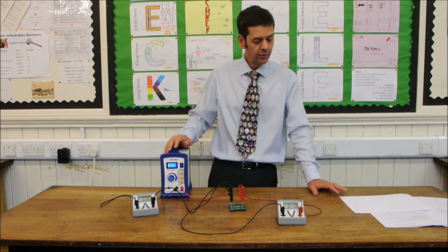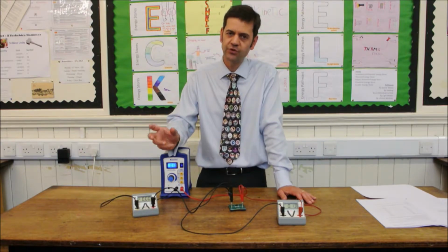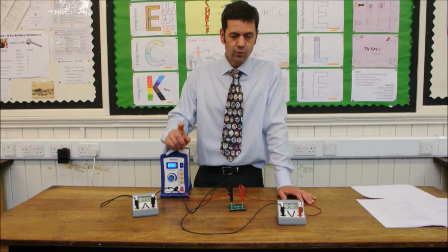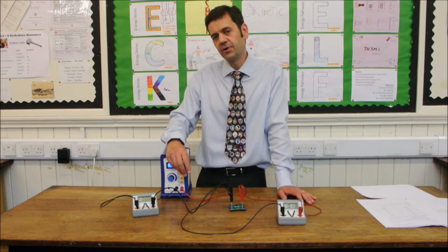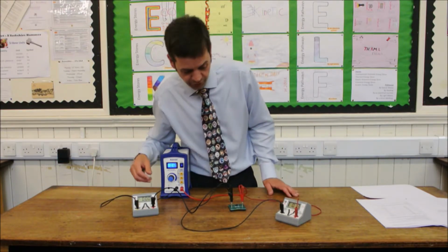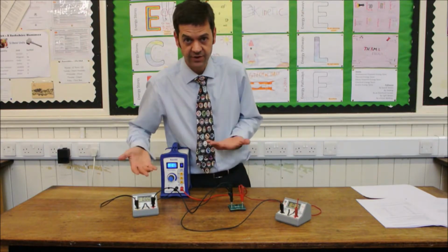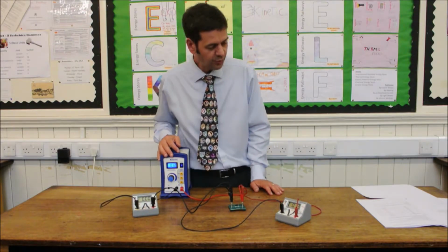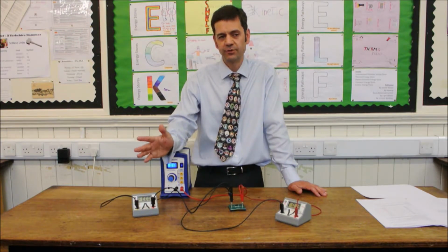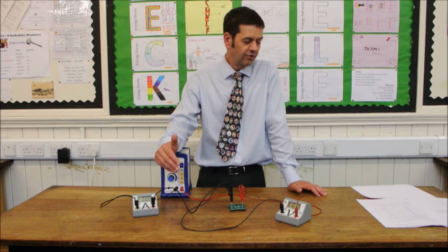Now this is where we need to increase the potential difference in very small steps to reveal the correct characteristic. So what we've chosen to do is to increment by 0.1 of a volt. We'll start off as close to 0.1 as we can get, and for this supply that is 0.13, and then we'll increase by 0.1, 0.2, 0.3, 0.4, all the way to 1.0 volts.